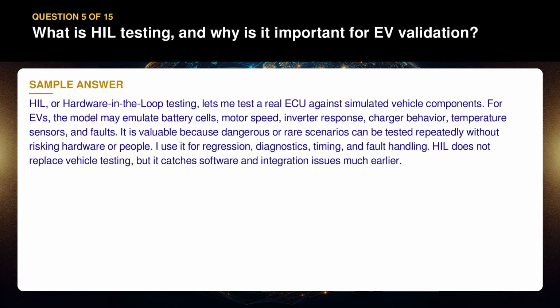It is valuable because dangerous or rare scenarios can be tested repeatedly without risking hardware or people. I use it for regression, diagnostics, timing, and fault handling. HIL does not replace vehicle testing, but it catches software and integration issues much earlier.